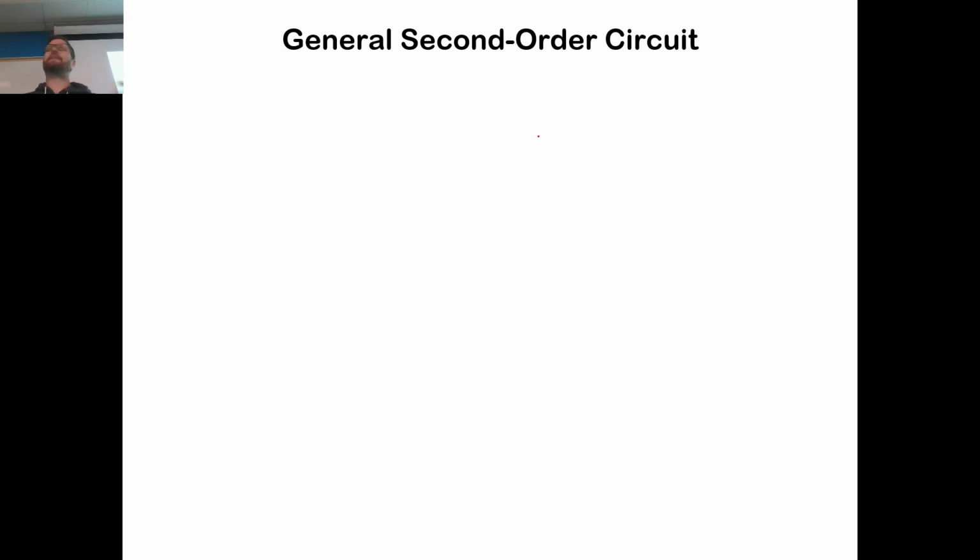Because it's going to have some characteristic equation. It's a second order circuit, so it's going to be a quadratic formula in terms of s, and it'll have different characteristic roots. So you can't just use the standard alpha and beta values we've been using for the series RLC or parallel RLC circuits. You have to start from basic principles and derive them.